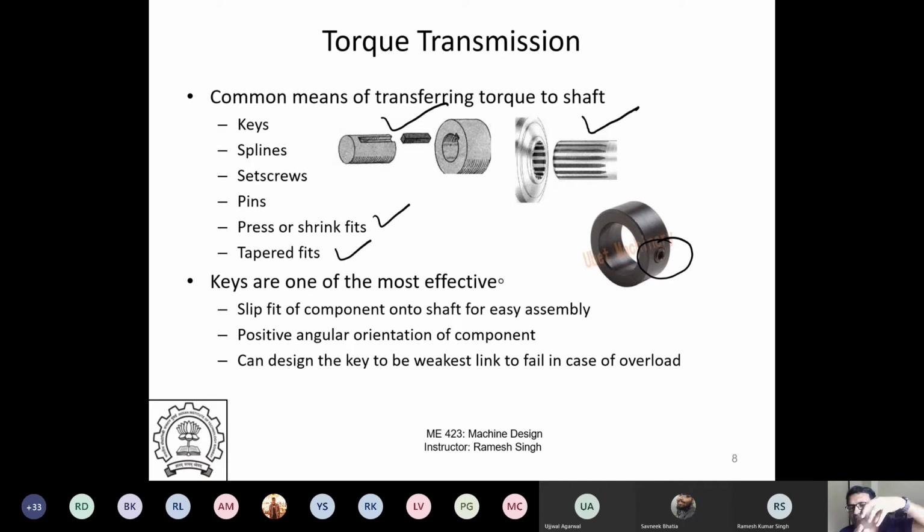So what they do is they actually just make a perfect fit and clamp it very tightly. They don't do shrink fit because I have to keep on changing tools there. The shrink fit is not an option, but in a lot of these precision bearings, they actually do shrink fit. They will take the bearing, heat it in the oil, and put it on the shaft. So the centers are almost at the same point. So you have similar centers, so there would be very little eccentricities, and that would lead to very little vibrations. Okay.